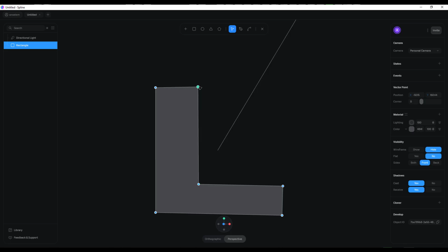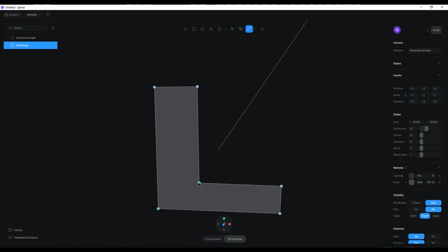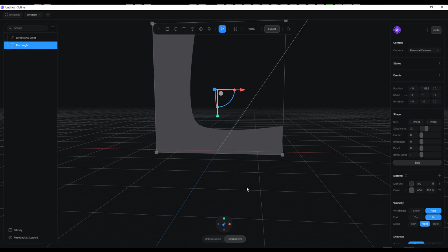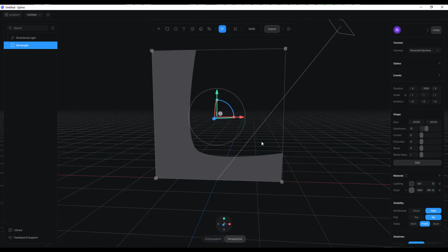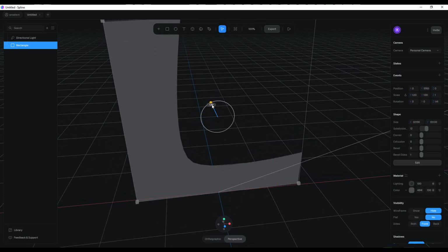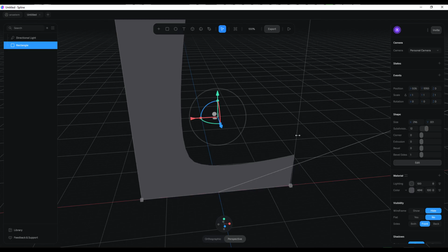So once we have this going, if you would like to bend, you can simply use the bend tool, and with the bend tool, you can add curves. So this way you can now simply change this from a linear to a spline curve, and that would be very nice. Now, regardless of this, if you also have your object selected, you can use the parametric gizmo to move things. Now, the parametric gizmo in itself is a very nice tool because in this case, you can choose to rotate if you want, scale if you want, and you can translate at the same time.